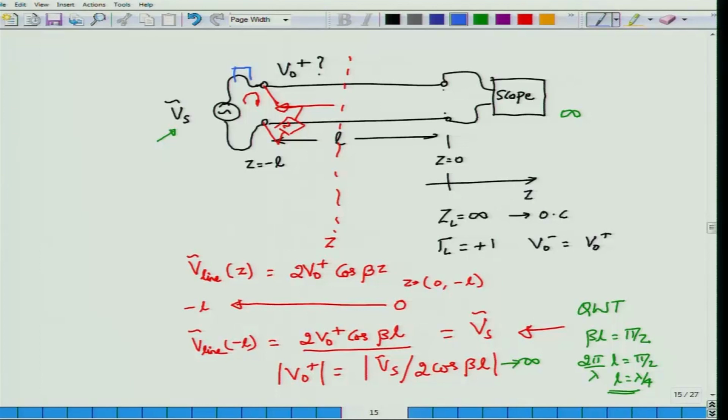And most importantly, we have considered transmission lines to be lossless, which more or less can be okay for the majority of applications. But I simply cannot find an ideal voltage source, because if I could, no matter how much current I draw, I could have the same voltage maintained at the source output terminals and therefore obtain an infinite amount of power. Clearly that does not happen with any voltage source in practice, because in practice you always end up having a certain amount of source impedance Zs.